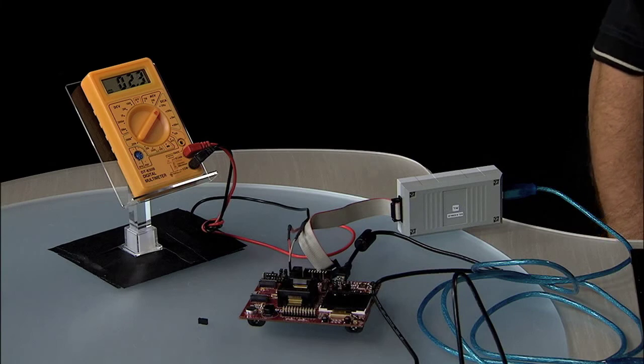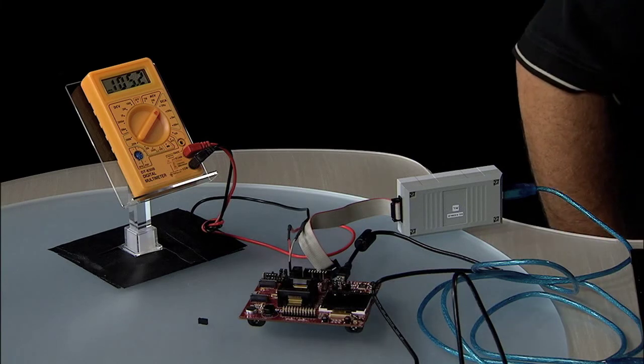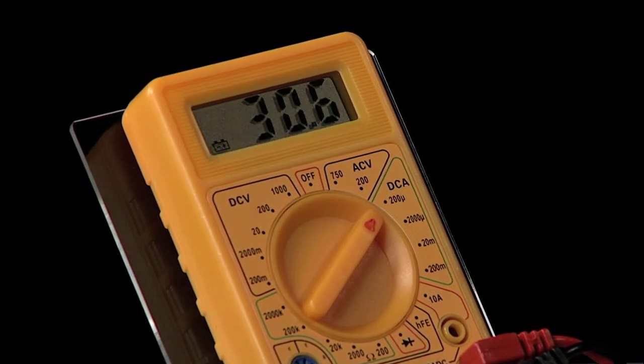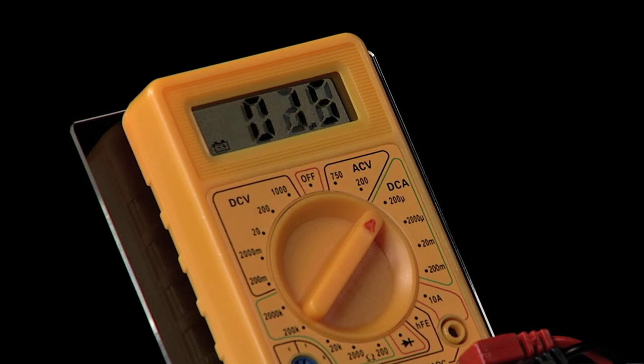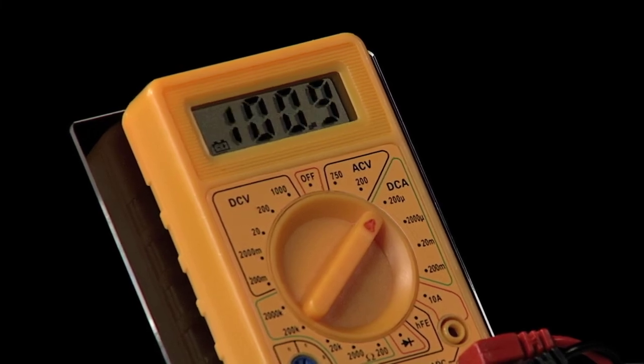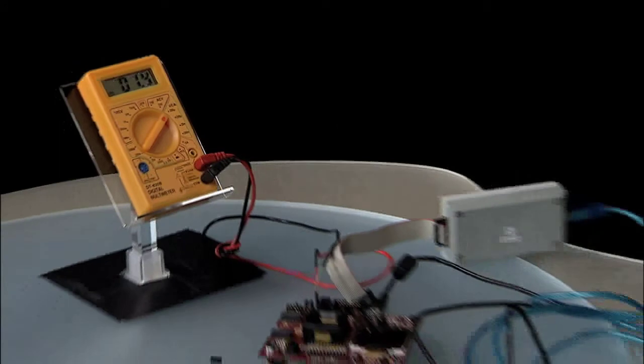Now at this point, if you look in step 10, again, because of the timer delay and the meter's inability to quickly move around for us, you can see we're jumping back down to 1.4 or so, somewhere in there. That's 1.4 microamps. And then the amount of current it's drawing in the meantime, according to our diagram, is jumping up to 252 microamps, but that's hard to see on the meter. So I'm going to write down 1.4. That's where we are for the majority of the time.